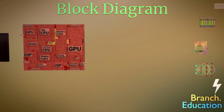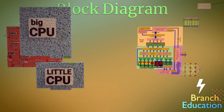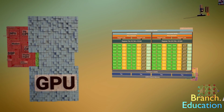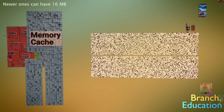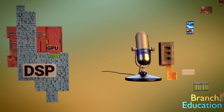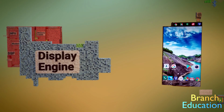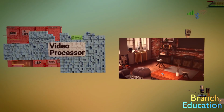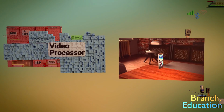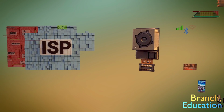The key areas in the SoC are the CPU containing multiple cores, the GPU which renders graphics, the shared memory cache which is usually around 4 to 8 megabytes, the digital signal processor which interfaces with things like the speakers, microphones, sensors, and many other things, the display engine which communicates with the touchscreen display, the video processor which compresses and decompresses images and video and enables 4K video recording and playback,